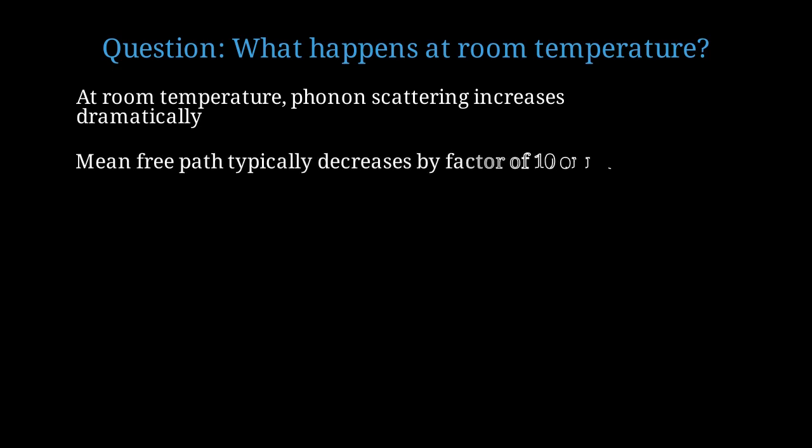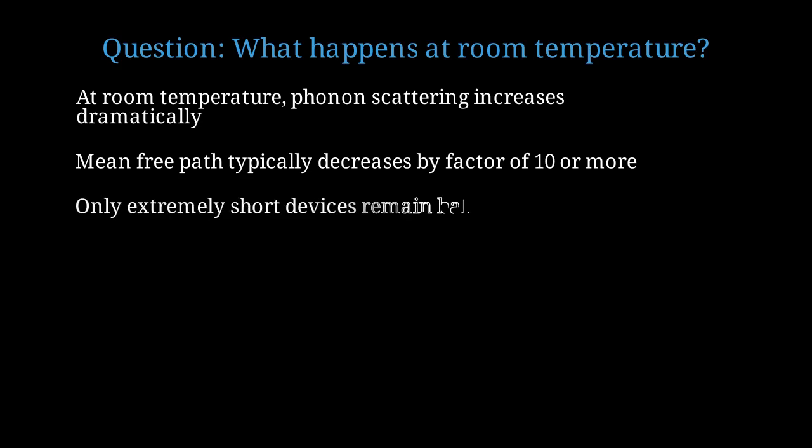The mean free path typically decreases by a factor of 10 or more compared to cryogenic temperatures. This makes ballistic transport much harder to achieve. Only extremely short devices, typically below 5 to 10 nanometers, can remain ballistic at room temperature. Most practical devices operate in the quasi-ballistic regime.